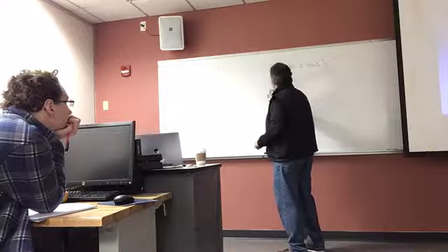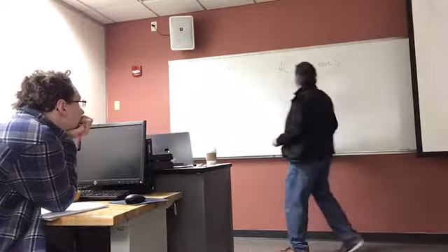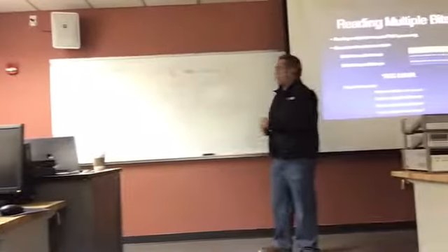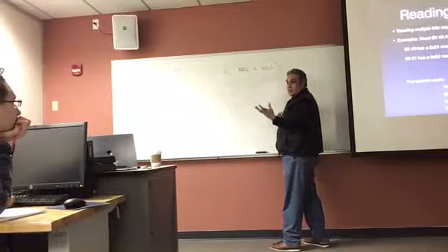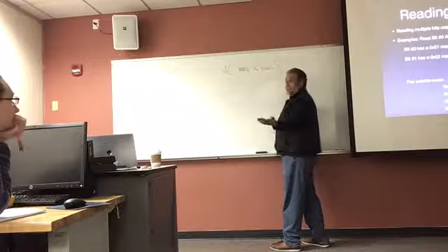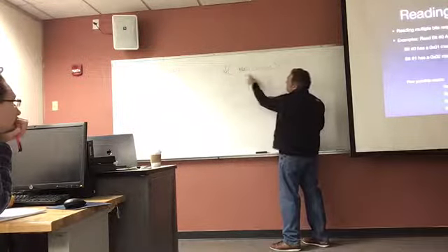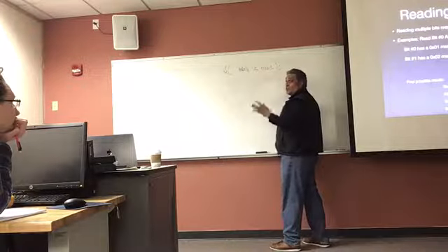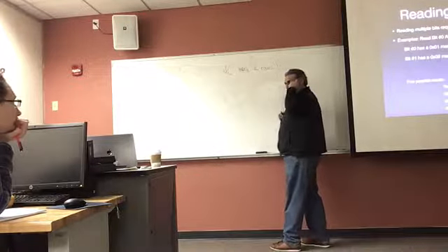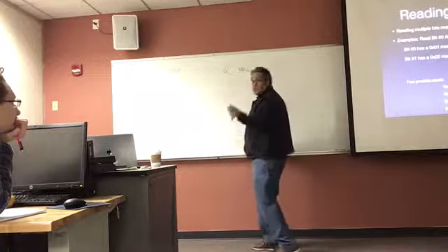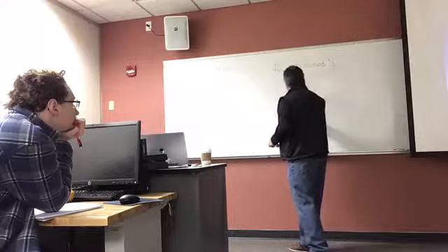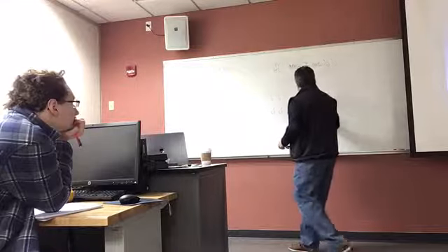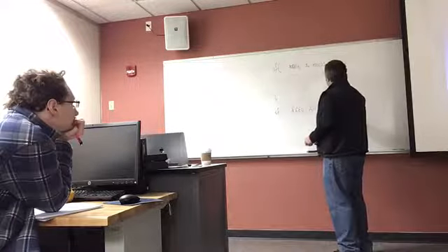And this if statement is actually constructed properly, because the answer to this is either numerical 0 or it's going to be numerical 1. So the only thing that this could be is either true or false in a C sense, right? What Josh is asking is what happens now if I do this? If I take that register and then I AND it with a 3.